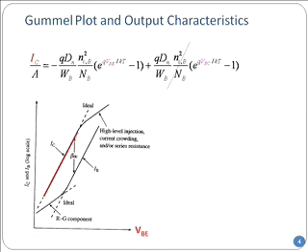So let's focus on the collector current I_C as a function of V_BE, and let's focus on the red line where I show the I_C is increasing with V_BE. Now do you realize that if I had it in a log-linear plot, then it should be a straight line? You do see that, right? Because if you take a log of I_C over A, being the area, which I am assuming the same for both emitter and collector, then the exponential, whatever is the prefactor, that will become a constant, and q over kT would be the slope. And so that is my first curve.